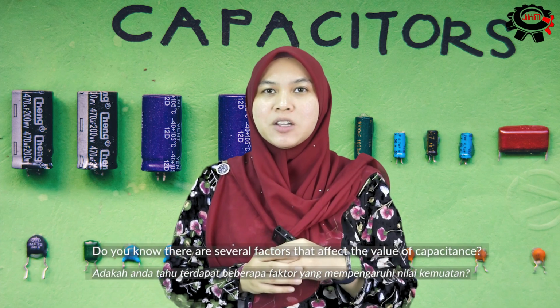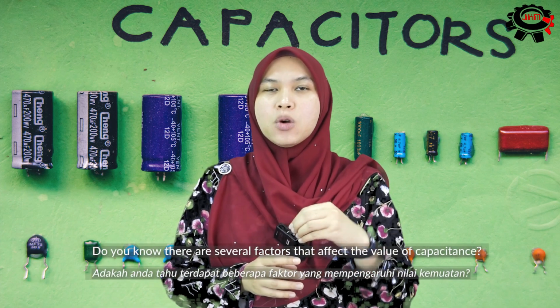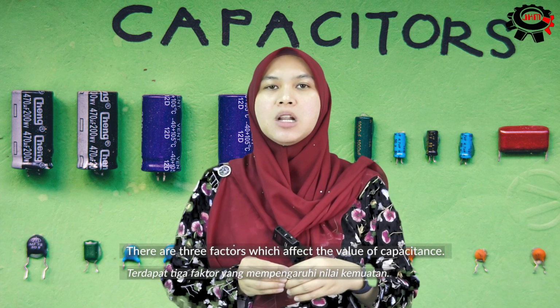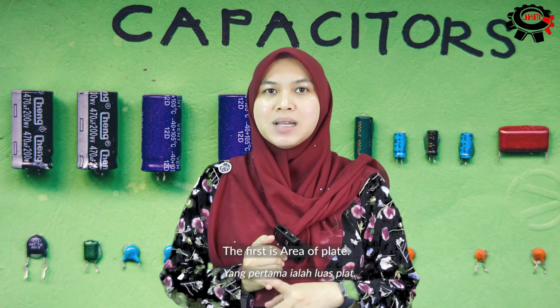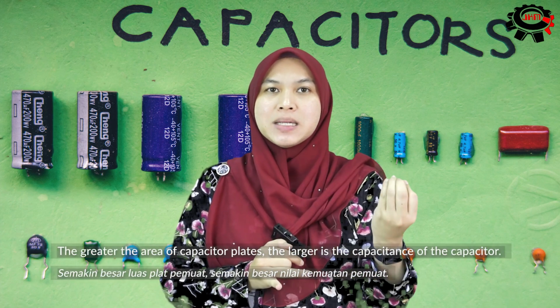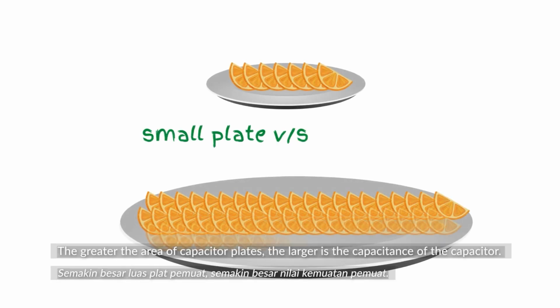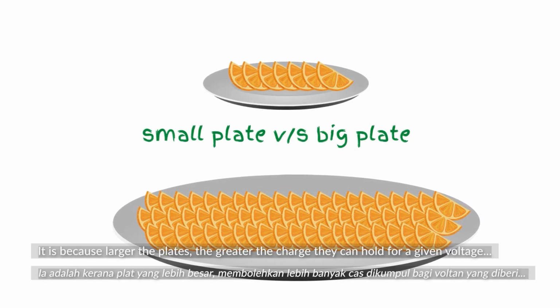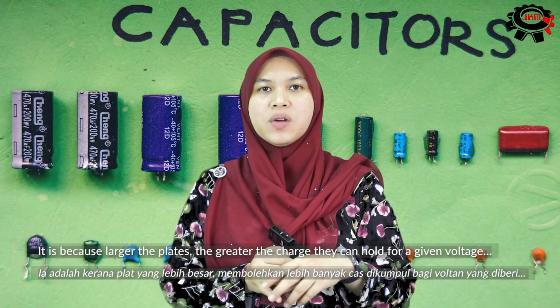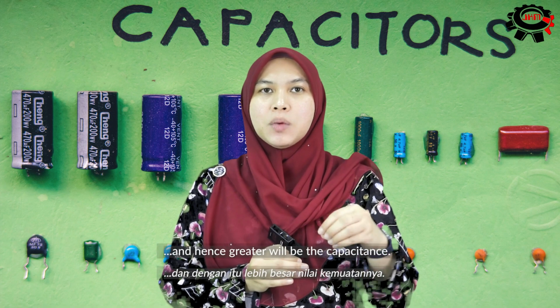Do you know there are several factors that affect the value of capacitance? There are three factors which affect the value of capacitance. The first is area of plate. The greater the area of capacitor plates, the larger is the capacitance of the capacitor. It is because the larger the plates, the greater the charge they can hold for a given voltage, and hence greater will be the capacitance.